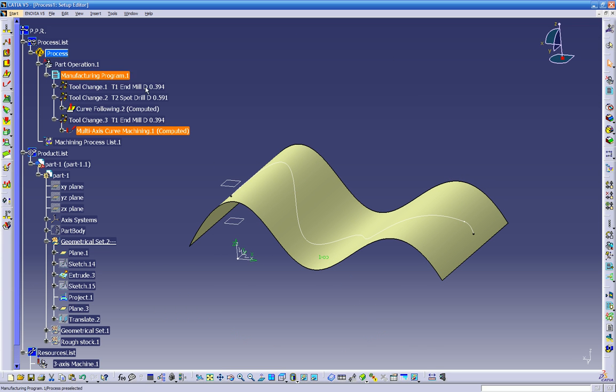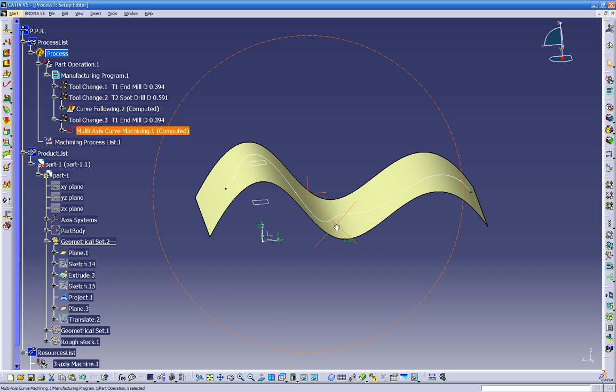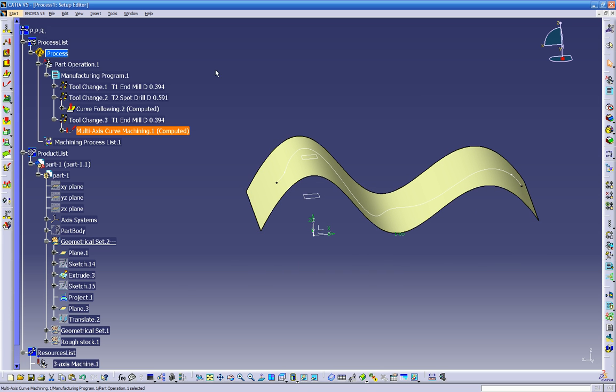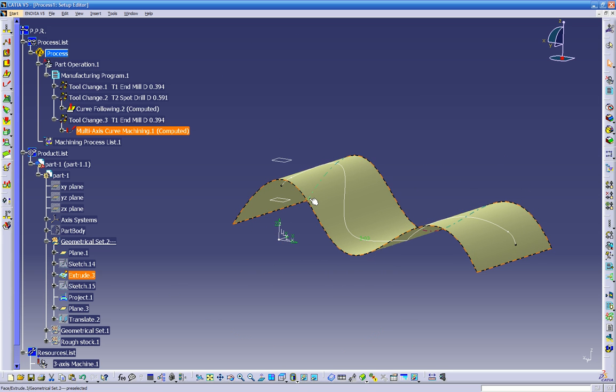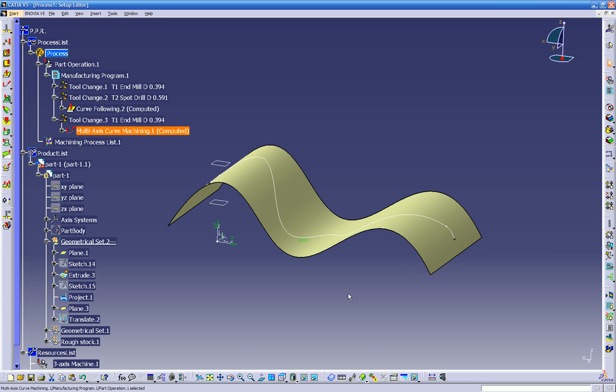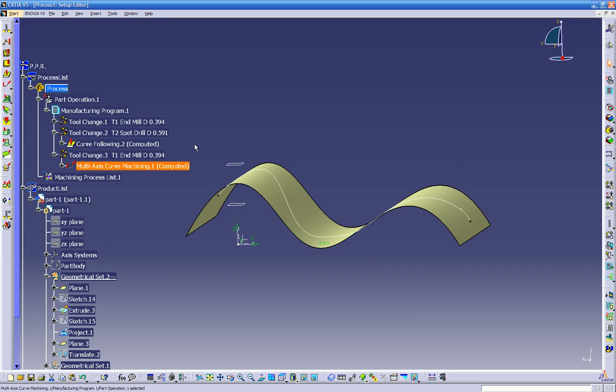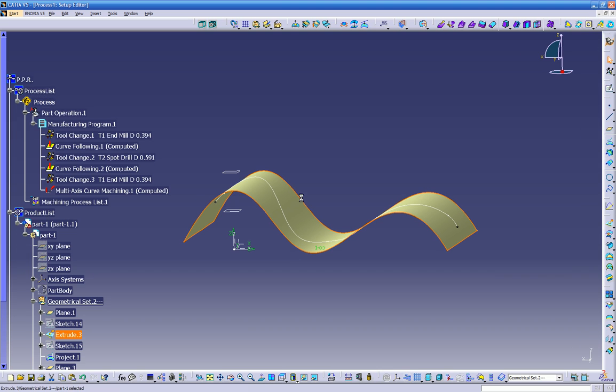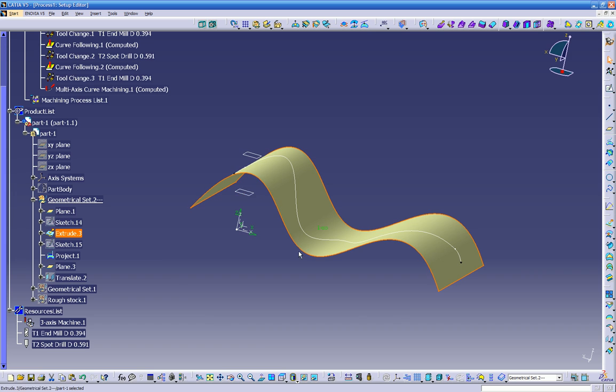And our next option I want to show you is point to point. This is pretty self-explanatory. If you want to start the machine at one point and end the part, and you want the tool to go to this point, you just have to have the points created, and the tool is going to follow it. So let's create some points. Let's go back into our generative shape design. Just double click twice on the part. So we got the window for shape design.